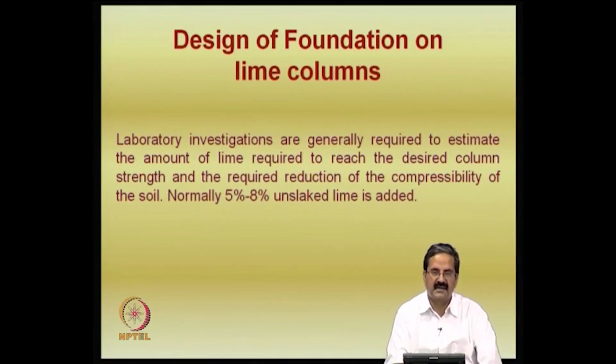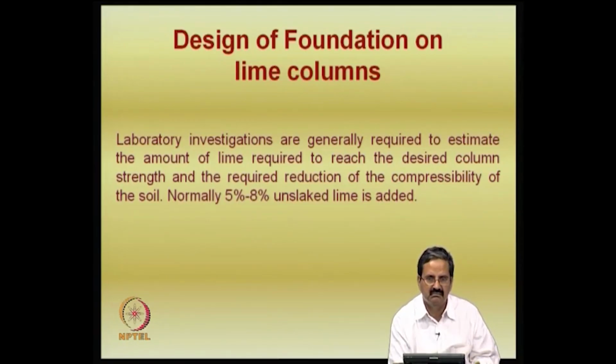What we should do, as I just mentioned, is take the unconfined compression test as the basis. Say, for example, you are trying to construct an embankment on a soft soil: take the soil at its natural water content, make a sample, add lime, make a sample and get its unconfined compression test, or all other properties. You need to estimate strength, compressibility, permeability, everything. Measure all the properties in the undisturbed state, and then measure them at various lime contents like 2%, 4%, 8% or whatever.